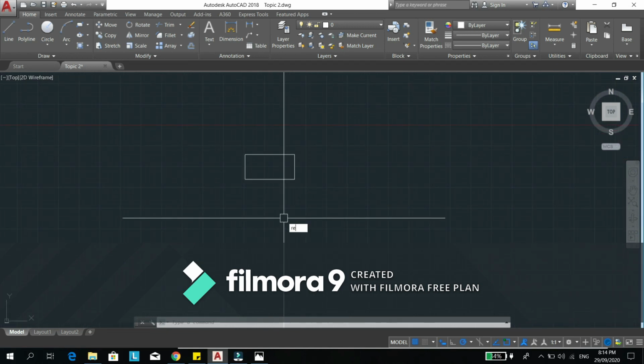When you type the rectangle, there are also other options in that command. Type REC and press enter. You'll see here the chamfer, elevation, fillet, thickness, and width. Width is the same as with the polyline, where we change the width of the line. For the fillet, you can create a round corner.